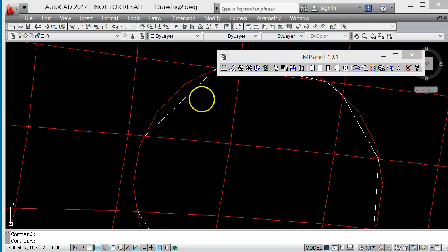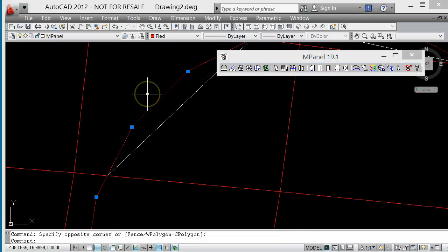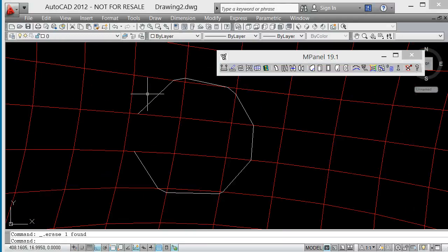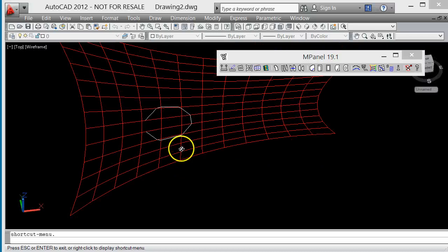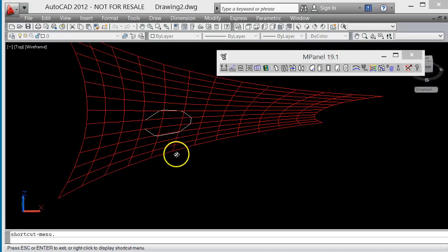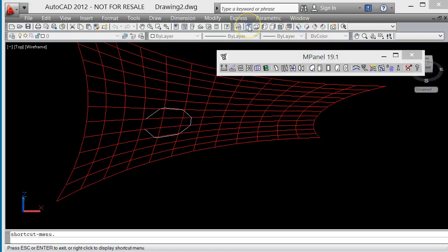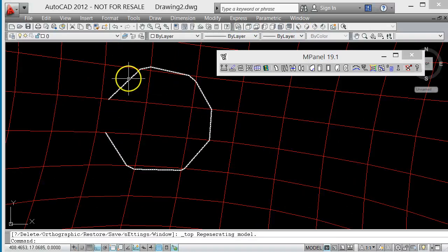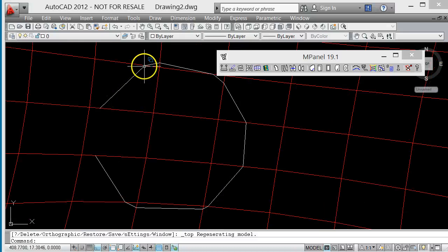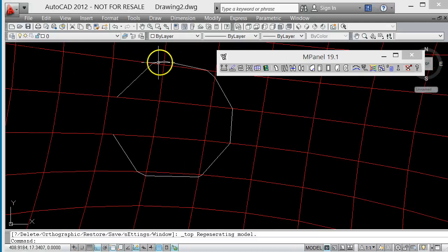I'll get rid of the 3D poly that is representing the circle, and we can see that we have a cross-section. This lies in the plane of the mesh, and because we've specified 0 as the number of points, that is no renumbering of the points, we have 1 point exactly at each point that the circular polyline before crossed one of the mesh threads.